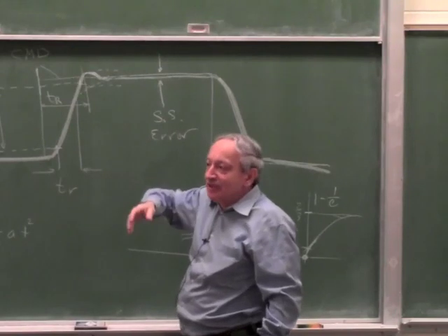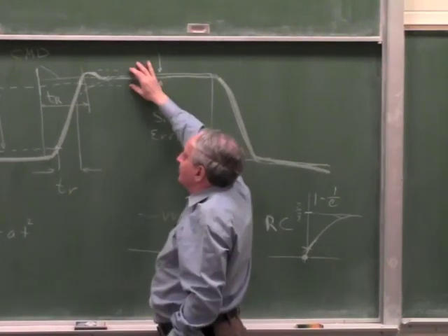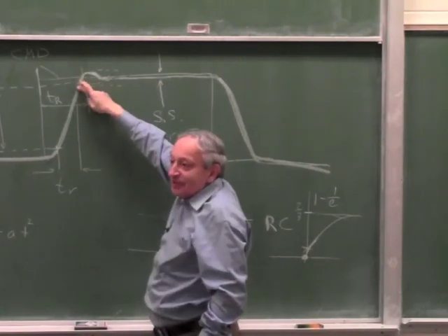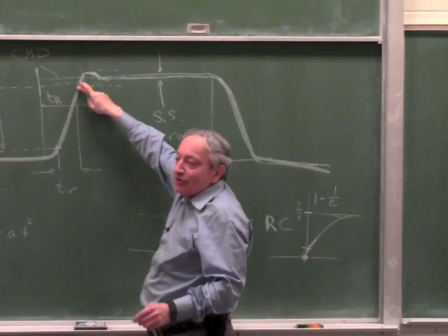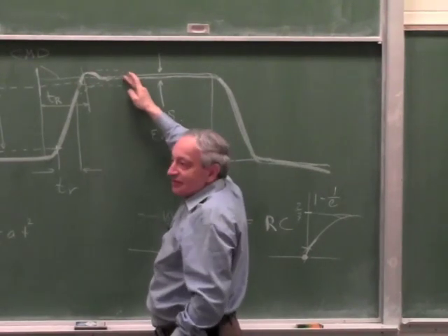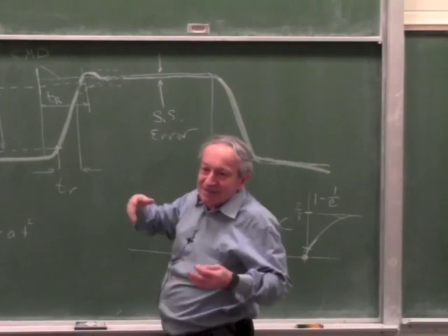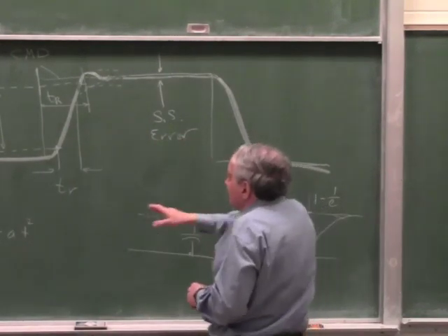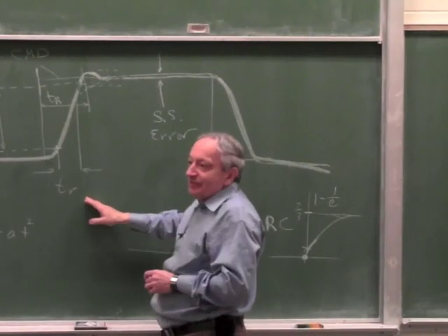If the servo is not critical, if it has to be within 10%, your response time will be up to this point. If the servo is a servo to 0.1%, your response time will be up to this point, because it's still settling. So the response time is a vague term depending on the need of the servo. The rise time is a more clearly defined term.